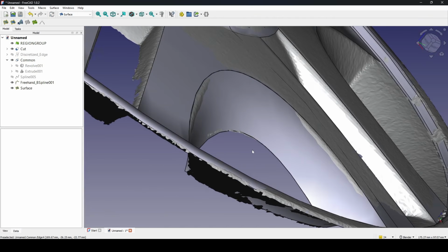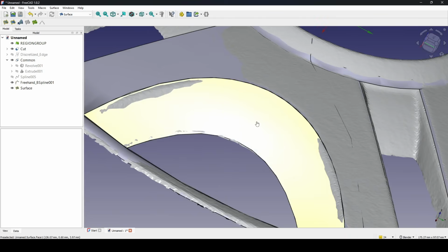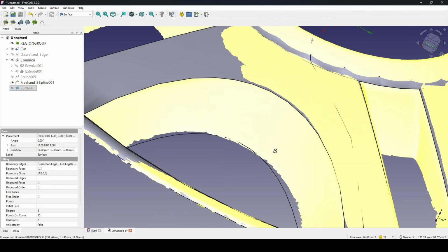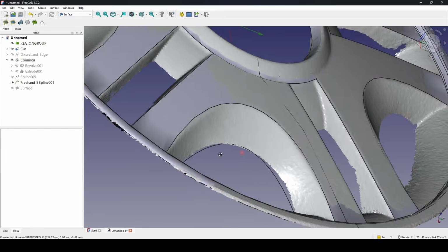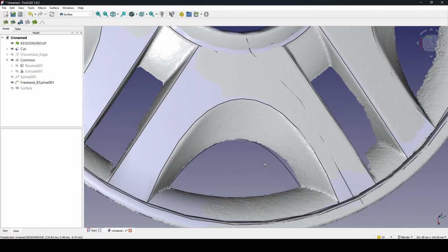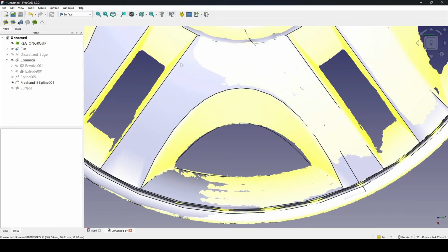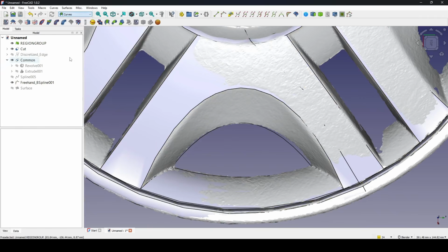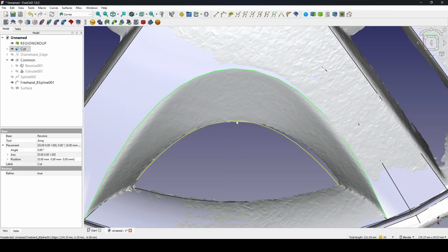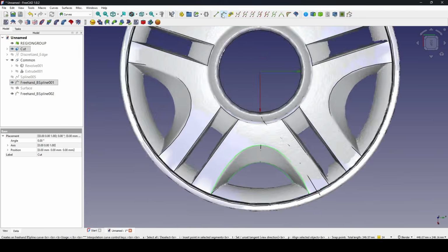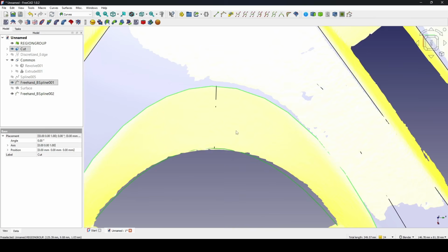Let's show the mesh, and you can see, because if I hide the surface, you can see the original one is much more flat in this way. So in order to control that, I can also go to the Curves Workbench. I can just select this line and then this line somewhere in the middle, create freehand display because I want this one to be flat.